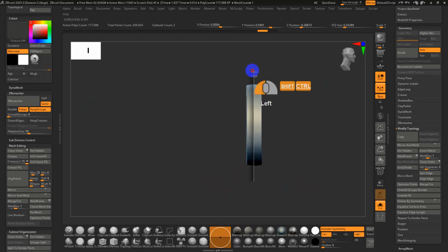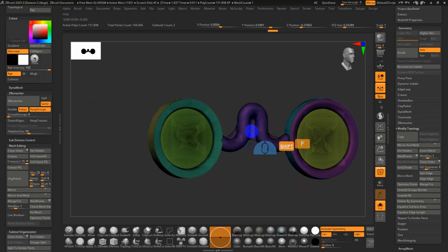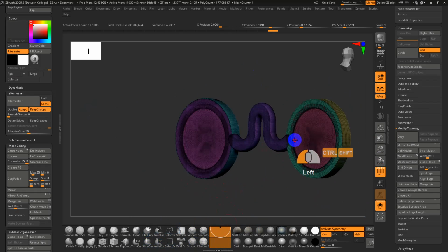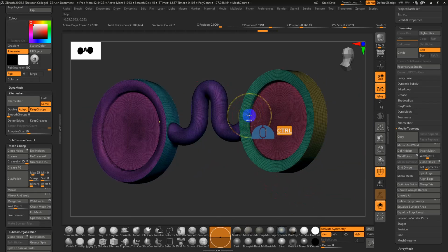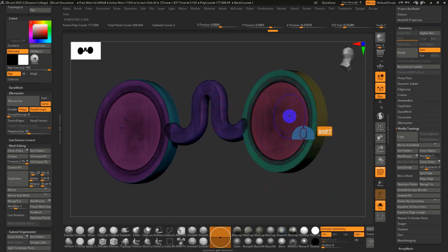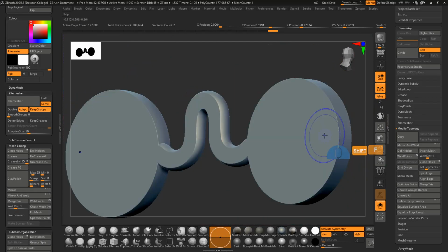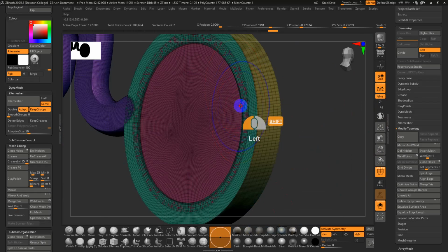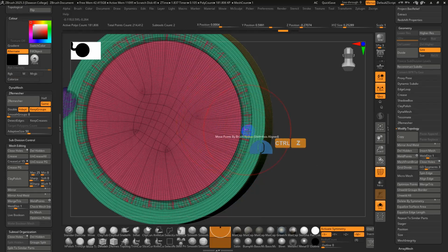Sometimes, by the way, I'll mention this. If you take a look at this, there is a problem with this creating a weird piece of filler mesh over here. So sometimes as an alternative, you can use Clip Curve. What Clip Curve will do is not kind of create a hole, which then creates a flatness, which then creates another problem. What it does is it just flattens the mesh against itself, okay? So it's the same mesh, but there will be another problem here in that we have this kind of like overlapping polygroup, okay? So what I recommend doing at this point, this would be a whole bunch of errors, okay? And if I try to, let's say, smooth it out, it could create some other mess.